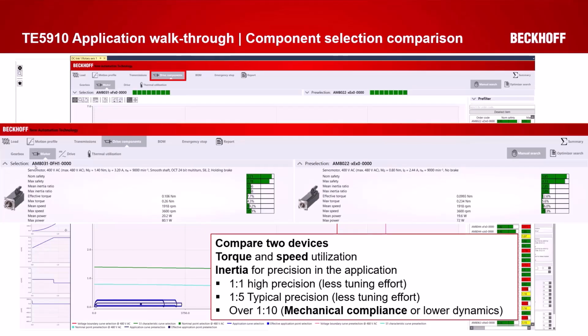And with this, you can go over a 10-to-1 or 1-to-10 inertia ratio on your mechanical side. We even have some applications that are 200-to-1 on the inertia ratio in the system.